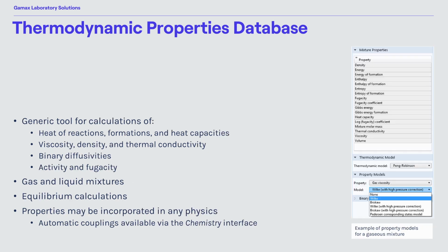Okay, properties database. As I mentioned a few slides earlier, these are important. If you want to calculate, let's say, conductivity or viscosity or density of the materials, sometimes there are huge gradients in the temperature field and velocity and maybe pressures. Then you need to correctly calculate and accurately model these variations, even if you are doing a stationary solution.